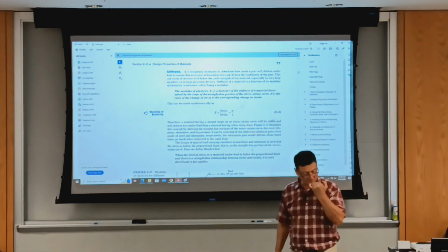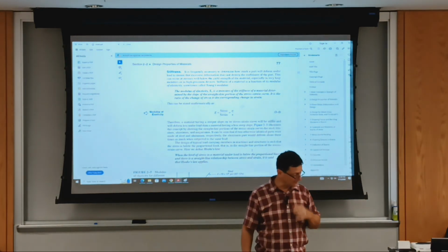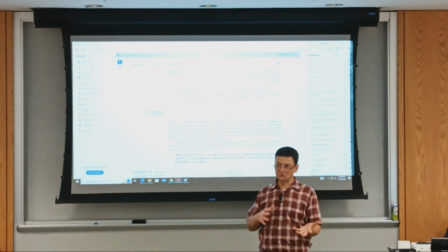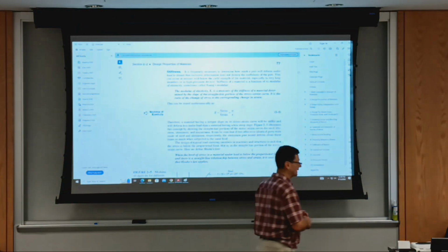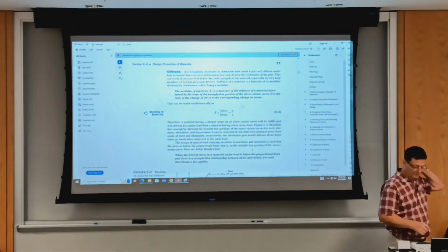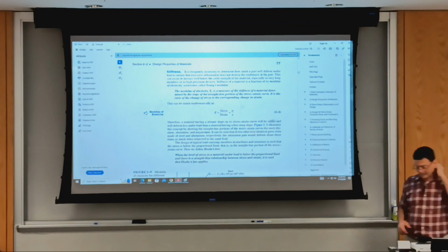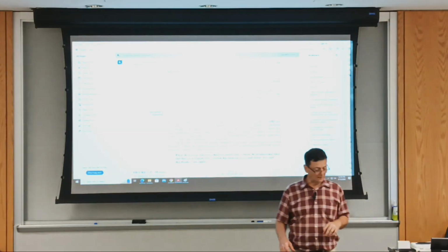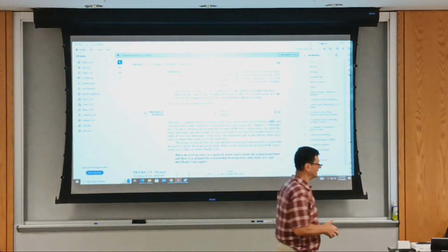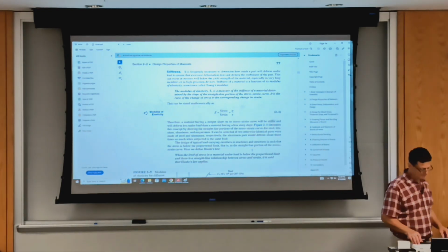Cast iron behaves in compression much better than in tension, and you can account for that in the shape design. If you have ever looked at C-clamps that were cast, they have a T section or an uneven I-beam section.